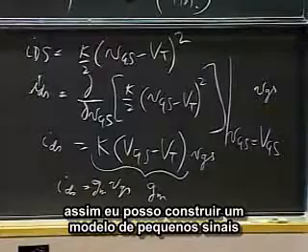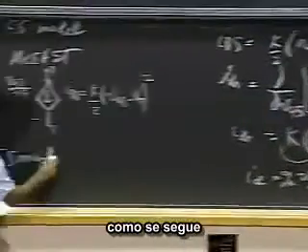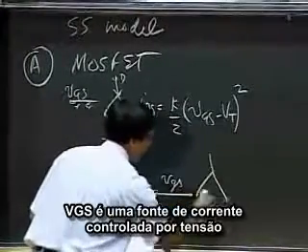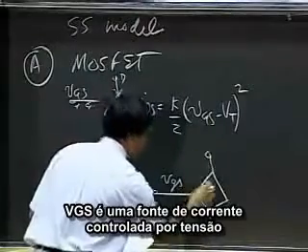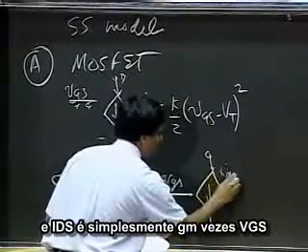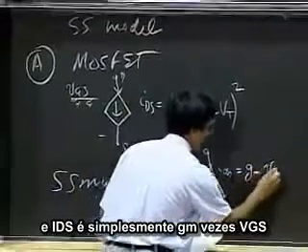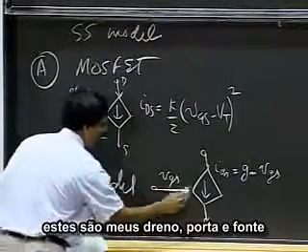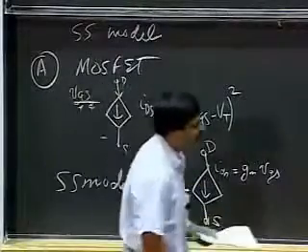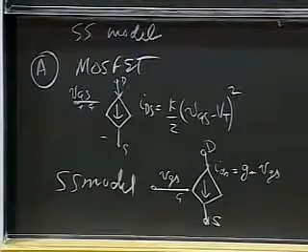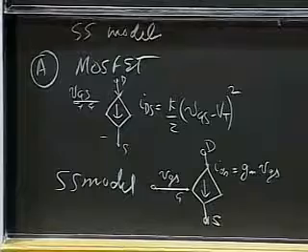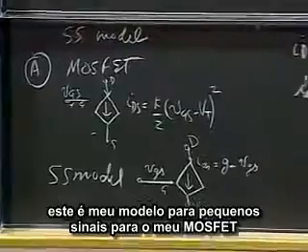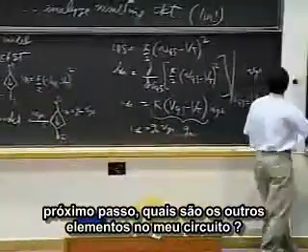Okay, so therefore I can build the small signal model as follows. Small VGS is a voltage-controlled current source, and IDS is simply GM VGS. Okay, so this is my gate, drain, source. So that's the small signal model for my MOSFET. So as the next step, let me...